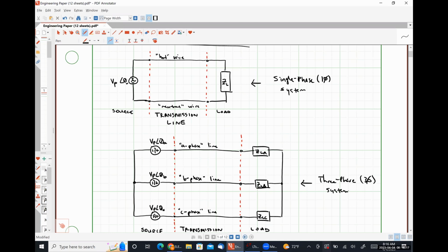Well, in a three-phase system, if you're able to deliver constant power, even using sinusoidally excited circuits, your torque is constant, your speed is constant, your vibrations are at a minimum, and the equipment will last a really long time. And by a really long time, I mean a really long time. We have three-phase motors across the street in Nethkin Hall that predate World War II that we still use to teach you guys, because it's nearly impossible to break them as long as they're connected to three-phase power.